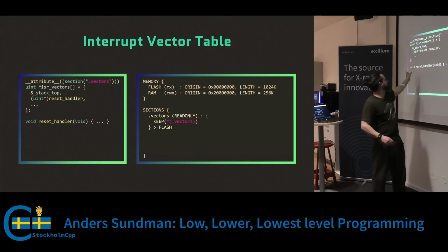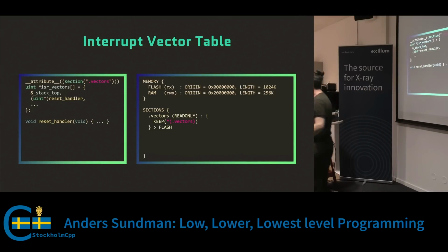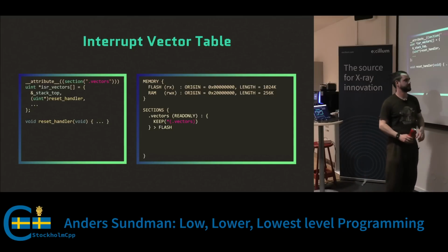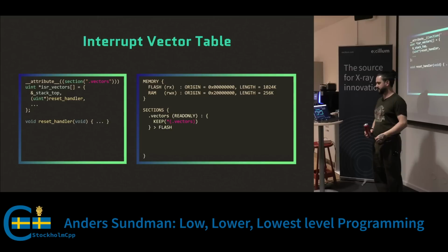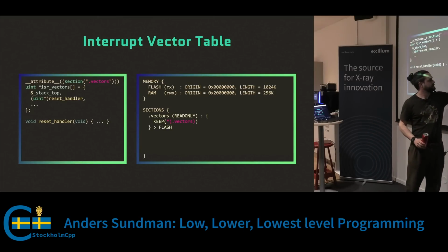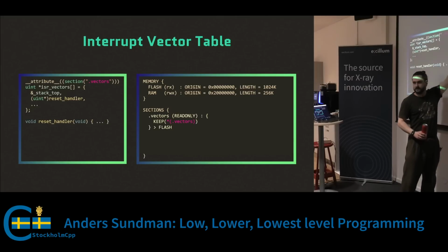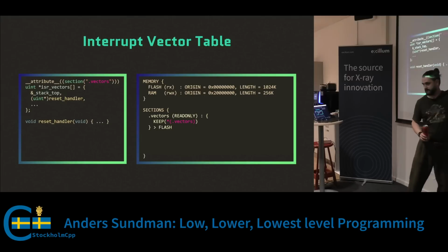The left side here is just the code from the last slide. And the right side here is a linker script. Now you are getting used to reading linker scripts. So what we see is we put something in Flash. If we make sure this is the very first thing in the sections, with nothing before it, then we know the Flash starts at 0000.